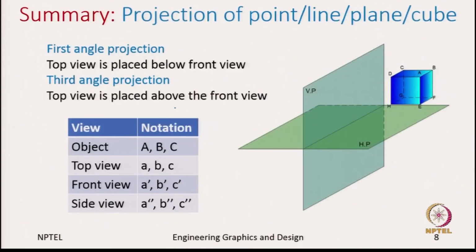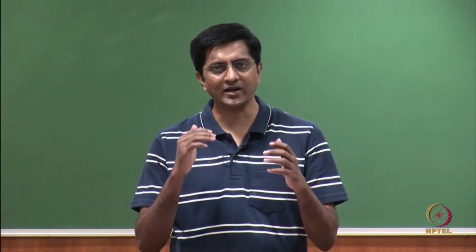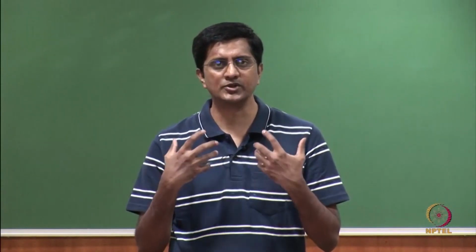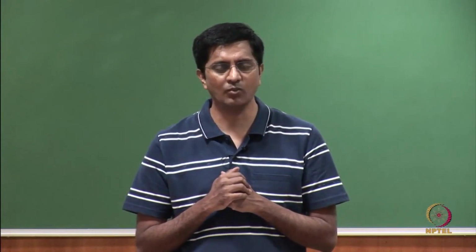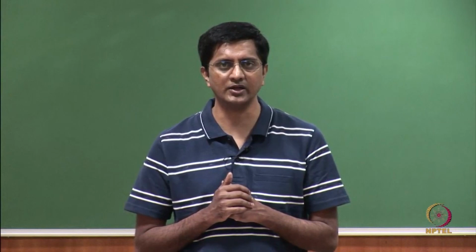So, finally, to summarize, in this lecture what we have learnt is how to project simple things like a point, a line, a plane, and a cube. The important thing to remember is, if your feature is parallel to the projection plane, you capture the true view. This is more important when we discussed projection of a line, a plane, and a cube.